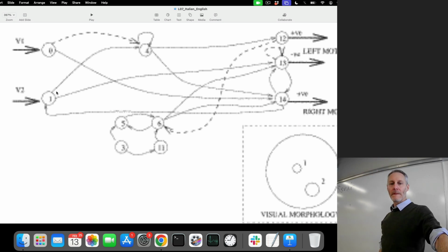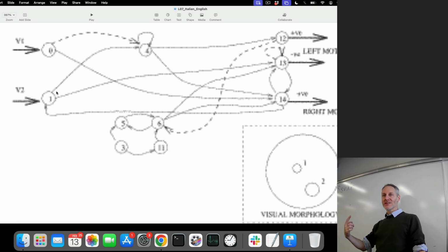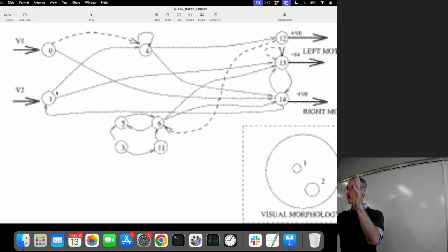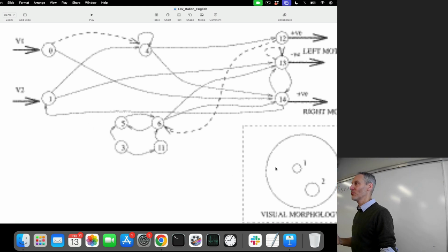So this is the video from the camera that can see 360 degrees under the table. So the frames that it's looking at are at 360 degrees. The frames are at 360. So here we go. Bear with me. Snapshot, snapshot, snapshot, snapshot, snapshot, snapshot. Put all those together into one big single image, and that's a view of 360 degrees around myself. Next time step, snapshot, snapshot. Make a second frame. That's what this circle is meant to represent. It's a panoramic view around the robot.